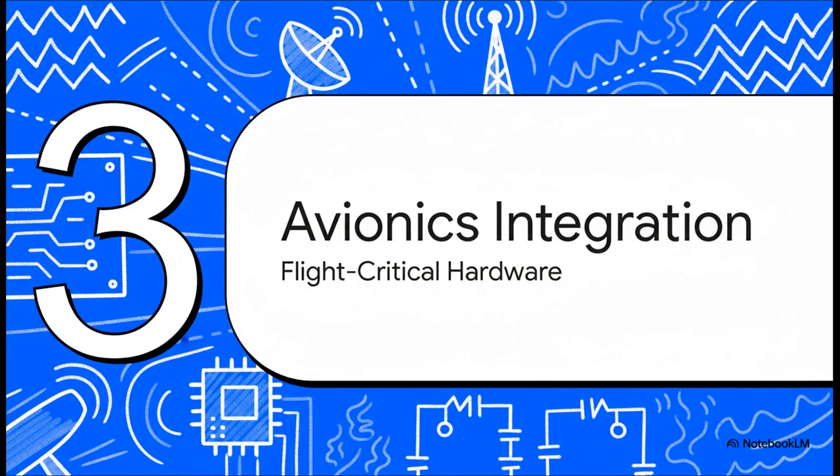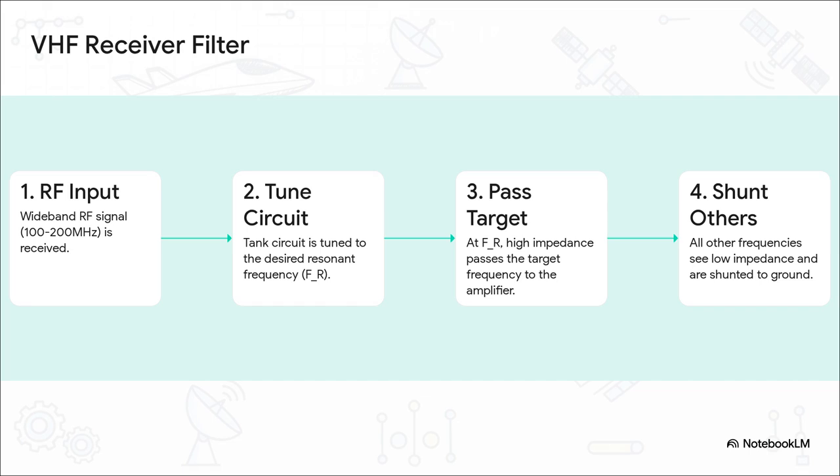These theoretical principles aren't just academic. They're deployed as tangible, flight-critical hardware inside modern aircraft's communication and navigation systems. A perfect application is the pre-selector filter for the VHF comms receiver in a Garmin G1000 class avionics suite. A wideband RF signal comes into the unit. The internal parallel tank circuit is tuned to the specific resonant frequency of the channel you want, let's say 121.5 MHz. At that exact frequency, the circuit presents a near-infinite impedance, which forces that signal into the low-noise amplifier. Meanwhile, all the other off-resonance frequencies see a very low impedance path and are just shunted directly to the airframe ground. This effectively isolates that one single channel you wanted.